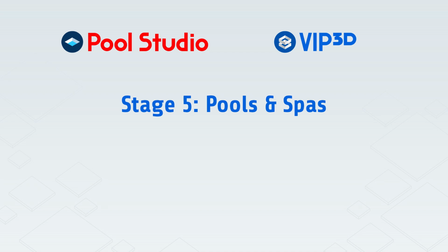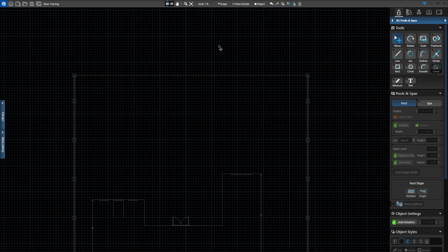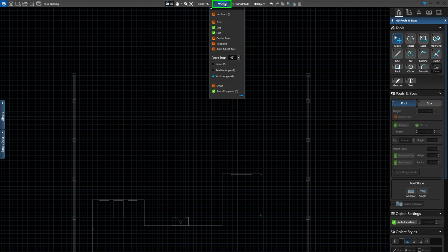This video will explain Stage 5, Pools and Spas. For this video, we'll set our grid to 1 foot and head to the Snaps menu to turn on Line and Grid. We'll also set the angle to World Angle and turn on Autocomplete.